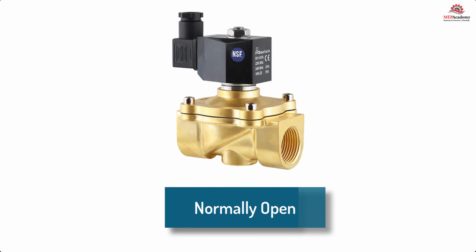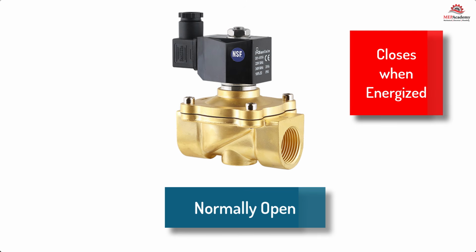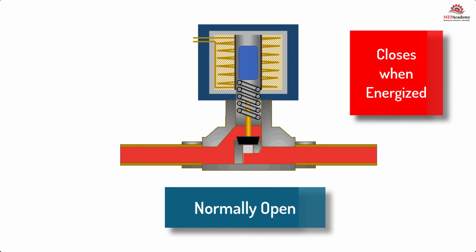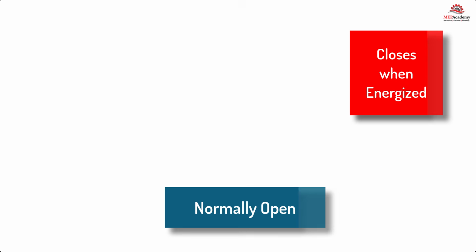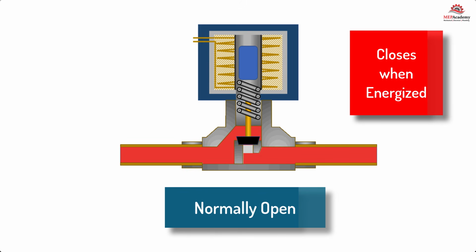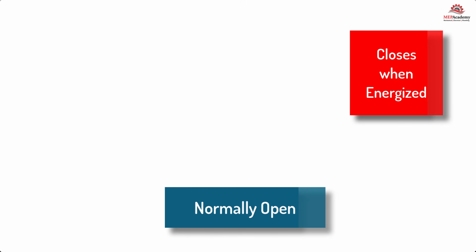The normally open solenoid is always open until power is applied to its coil windings. This is the type used for refrigeration pump down, as you want the flow of refrigerant to be unhindered until it's time to activate the solenoid valve and force close the valve. When power is applied to the coil, it pushes the plunger downward instead of pulling upward. This causes the plunger to close the valve. When power is shut off to the coil, the spring will force the plunger upward, opening the valve.